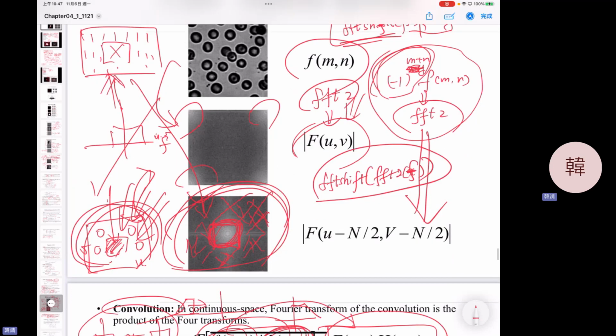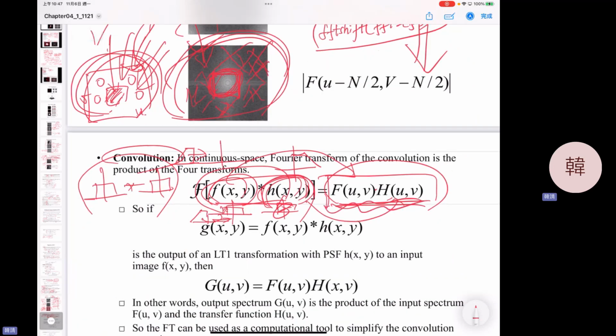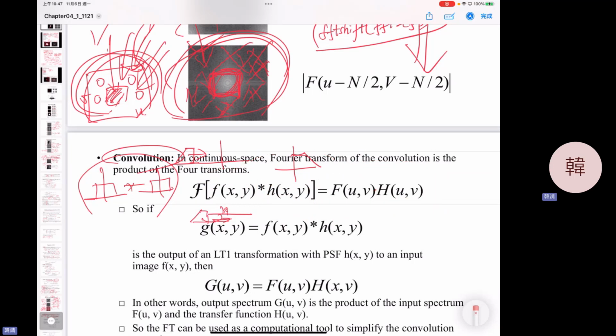So it's much easier to explain what your filter looks like if you only have to use a multiplication operation in the frequency domain. It is important to understand: if we change to the frequency domain, convolution is just like this. Convolution in the spatial domain is a very complicated operation, but in the frequency domain, you just use multiplication instead of convolution. It can be demonstrated. I think at the beginning I already showed that.